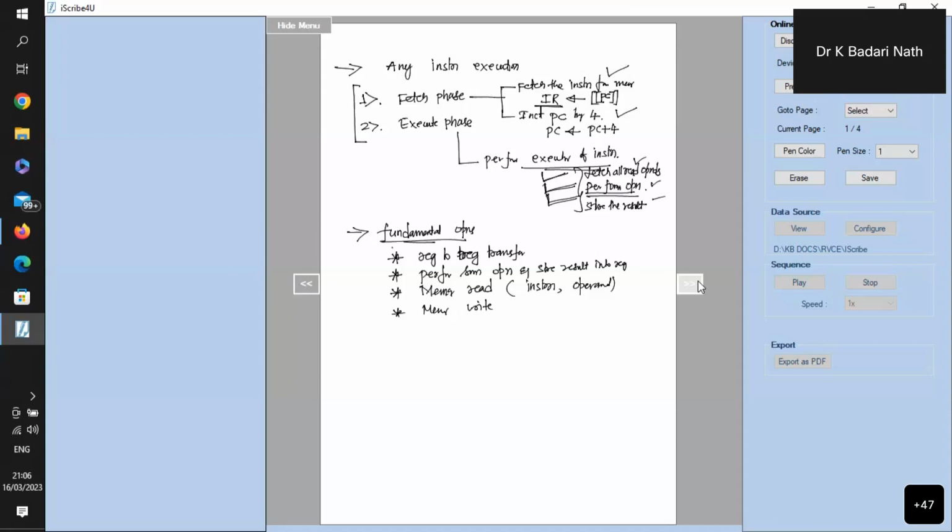So now we will see how each of these basic operations can be implemented by giving proper controls to the different blocks present inside the processor and make things work. We will take simple small operations before we go to the full instructions. Now, let's say I want to transfer the data from register R3 to R4. Let's say this is my requirement. So this can be one operation of this instruction itself.